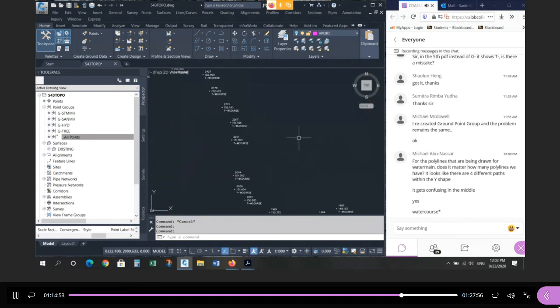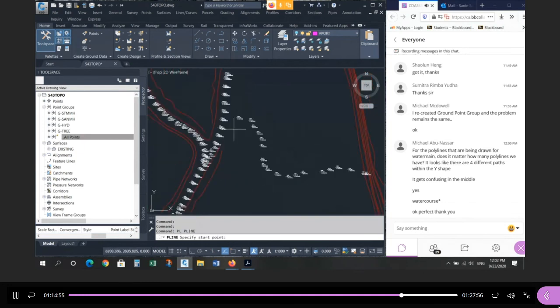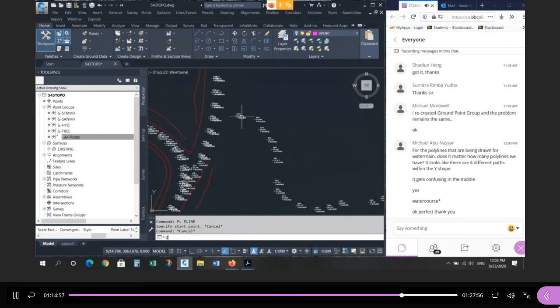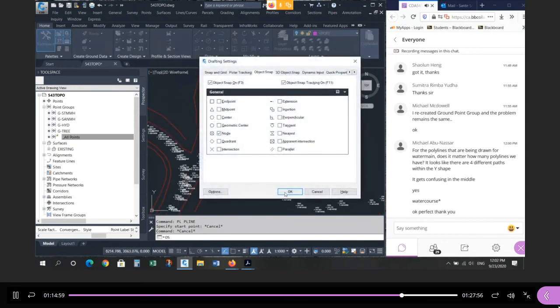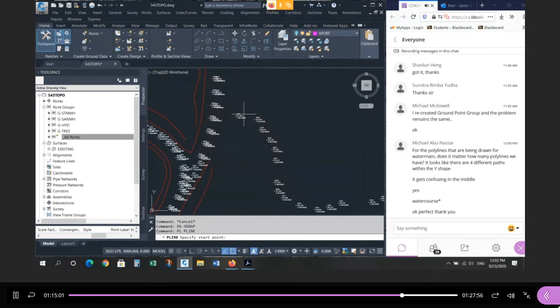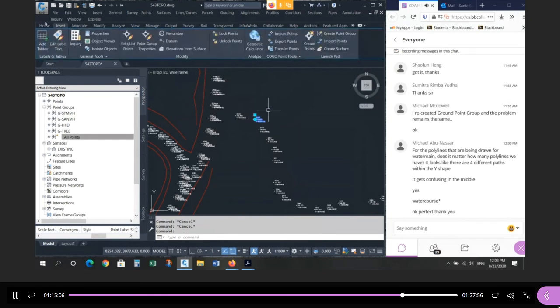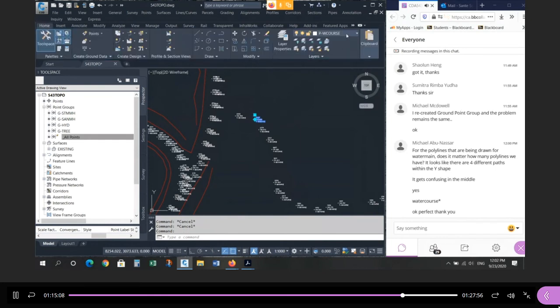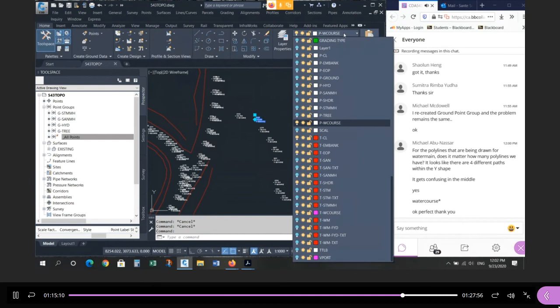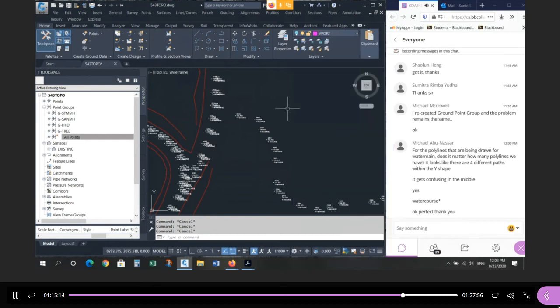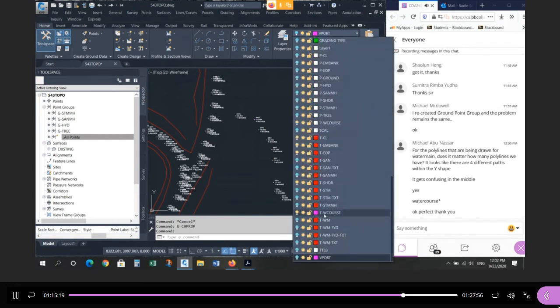Okay, so I can do this if I want, right? I can draw a polyline, connect the dot from, turn my O-snap to node, polyline, and then just connect the dots. And the current layer is off, sorry. So I want to be in a layer called T water course. And then I draw, oops, not the point. I want the current layer to be T water course.